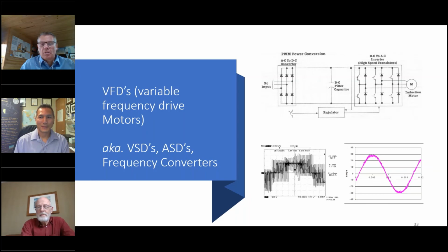Actually, this gas field is a sour gas field, the largest gas processing complex in Asia, in India, in Gujarat, Surat. And we find that possibly the dust conditions or the cooling conditions are not that good. And possibly we are still not using the closed motors. Mostly these are the open motors, and they are in applications in the sulfur recovery units, or the areas where we have more dust coming in.